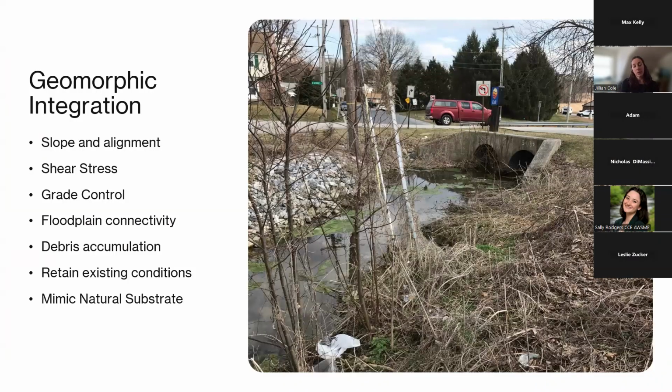And then when looking at how to incorporate the geomorphology into the design, we're looking at the existing channel slope, the alignment, evaluating shear stresses and velocity using the hydraulic modeling, looking at the floodplain connectivity of the channel and the potential impacts of that on the structure during flood flows, looking at the potential for debris accumulation. Is there a lot of loaded debris in the channel? And then trying to maintain the existing conditions of the channel as much as possible. So maintaining the upstream and downstream conditions to the extent feasible.